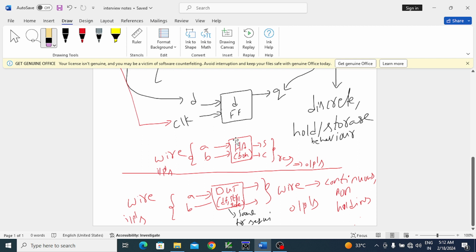So anyhow, the question and the straightforward answer: why are input ports wire and output ports reg in behavioral style? Because until getting the next output I need to store the present output. That's why output ports are reg in behavioral style. Input ports you don't need to store like that.